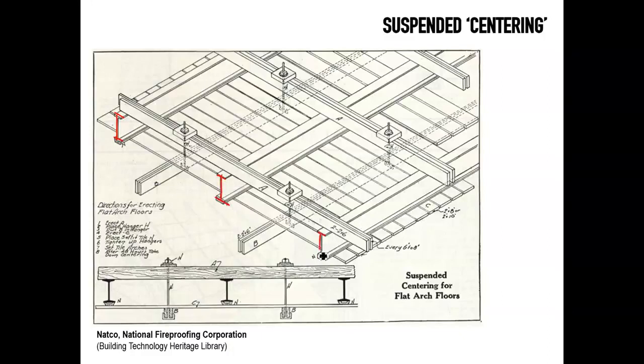There's 3 of them, and then you have a number of 2 pairs of joists running from end to end continuously over another beam in the middle, and then we have a series of bolts that are used to support a scaffold, or something that is more similar really to a decking for concrete, although in this case it's used to receive these clay tile blocks while it's still getting built.